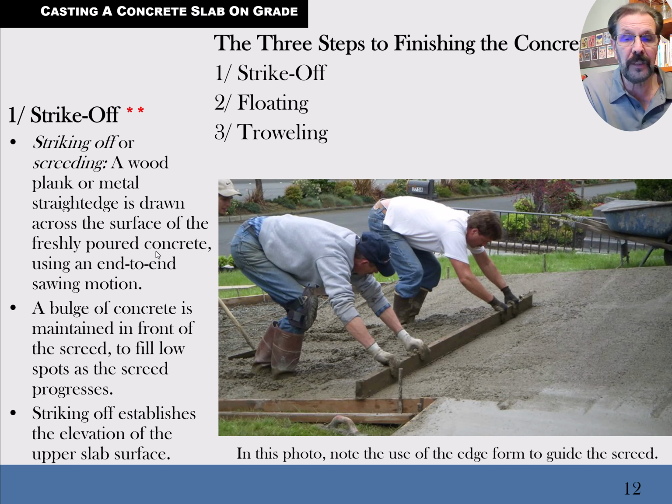If it's a house slab, a building slab on grade, then you want it level. And in many cases, you want level in the footings and everything else. But if it's a driveway like this, then you want it to be running at a slope because you want to send the water somewhere. So we always want outdoor slabs to have some kind of a slope on them, about a 1 or 2 degree slope, about a 1/4 inch per foot, 1/8 of an inch to a 1/4 inch per foot slope, that kind of thing.